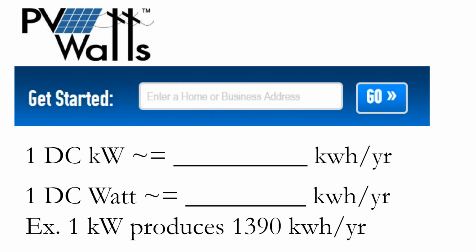So the same data set that feeds PVwatts, which is a free, accessible online software put out by National Renewable Energy Labs, they're an offset of the Department of Energy, that same data feeds your commercial design software. It's just that the commercial design software gets you further into the design, but PVwatts is just very good for saying, well, how much is my solar array going to produce?